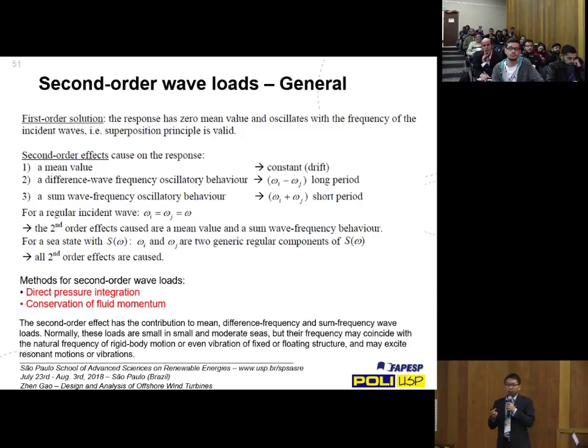And that is the first order wave loads, and typically we use the boundary element method, a numerical method, to solve wave loads for any type of floating structure in a linear sense. And then, of course, we usually also enter into second order effects. They are important wave loads for moored structures, where you have a relatively large natural period. The absolute magnitude of the second order wave loads is relatively small compared to the first order, but they might excite the resonant motion of the platform. So that is also important to get.